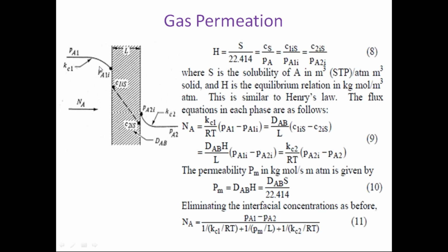Similarly, you can also estimate the mass transfer coefficients in the gas film, Kc1 and Kc2, because typically we can exemplify that one component is transferring through another component which is non-transferring, like A transferring through non-transferring B. The Kc, that is the film mass transfer coefficient, will vary depending upon the concentrations. That's where the Kc1 and Kc2 values are different.